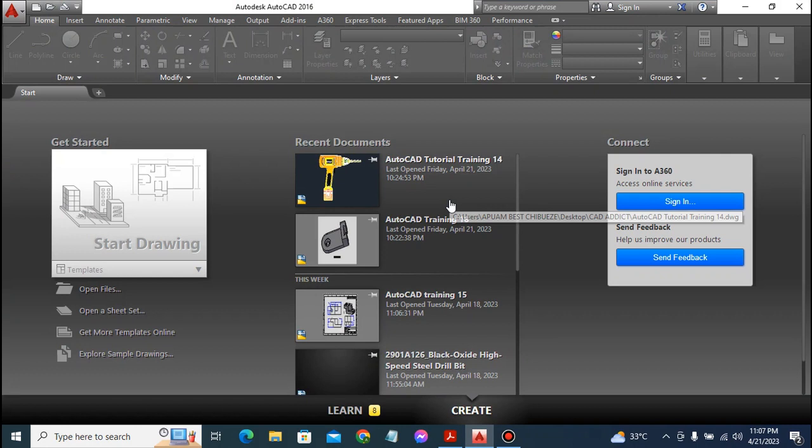Then under the coordinates, we have what we call the absolute coordinate system and relative coordinates. When you're talking about the absolute coordinate system, it measures points in reference to the origin. By origin I mean 0, 0, that point on your graph where all the points have to start from. That is the origin. Then you talk about relative coordinates. You are trying to locate points with reference to the last defined point.